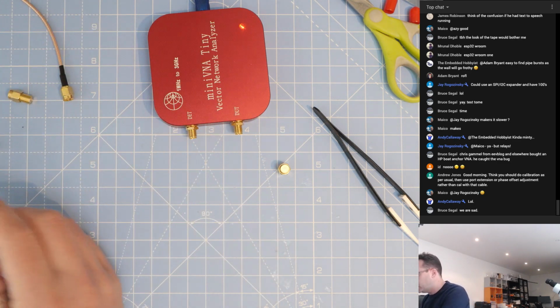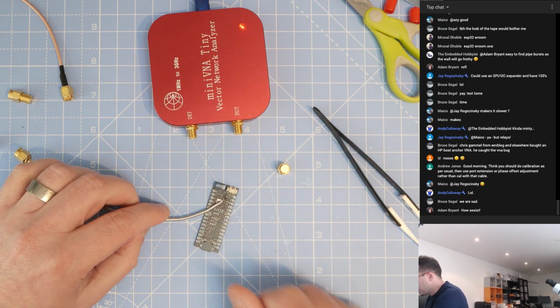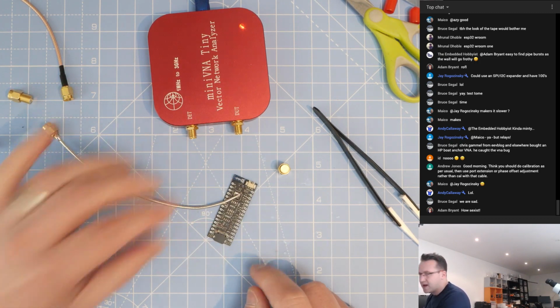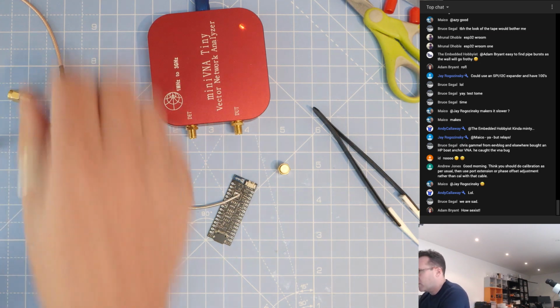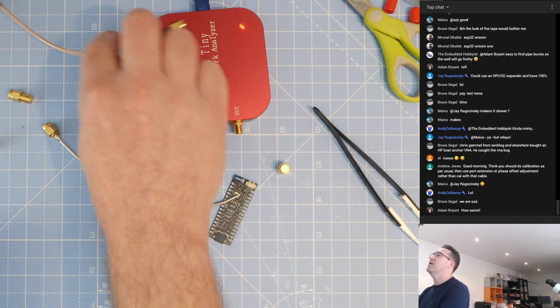Okay, I guess I'm going to have to solder a 50 ohm and an open. On a board, I have to get rid of the antenna to do it. Okay, so it looks like today I'm not going to be able to calibrate at a specific length.